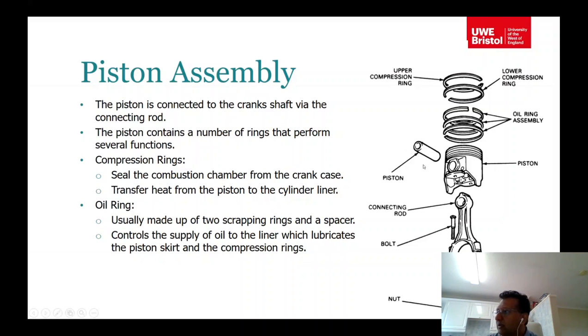And then this is not the piston, this is the pin, and that is the connecting rod. And these are bearing inserts. These bearing inserts act as bearings actually. They facilitate a low friction surface. And this is the cap, and those are the nuts.